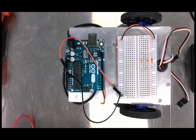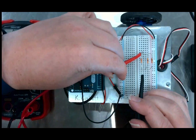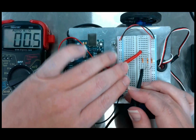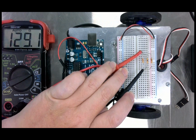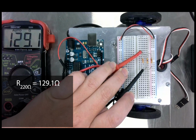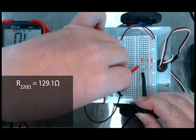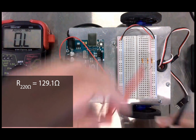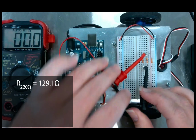Let's see if I measure across each individual one. Write down the values that you get. Y'all do this with me. So I'm measuring across the 220 ohm, and I get 129.1 ohms. Okay, well that's not 220, so I'm a little confused by that, but let's keep going. Just power through it. Let's measure across the 470 ohm resistor.